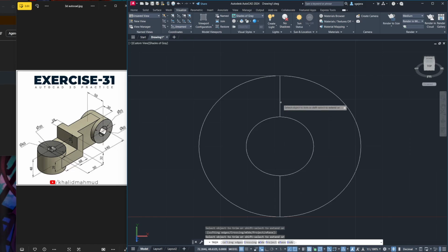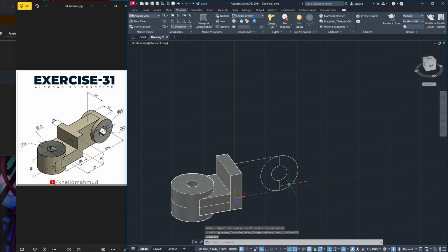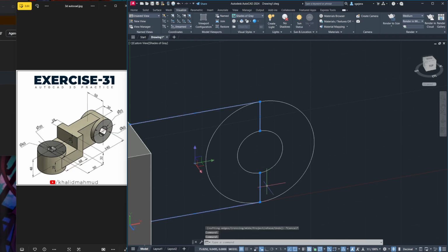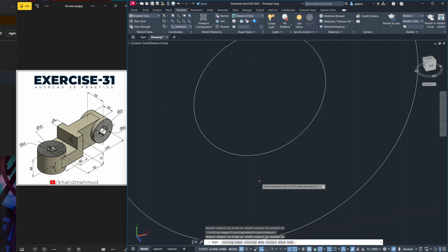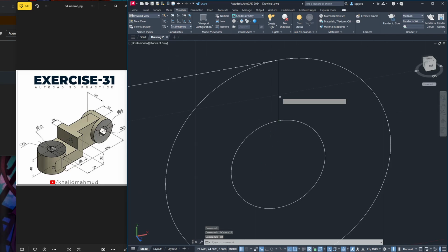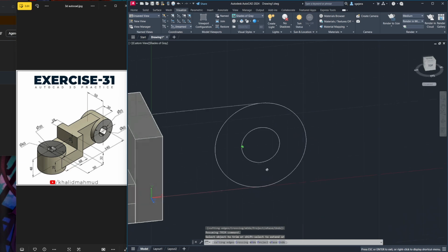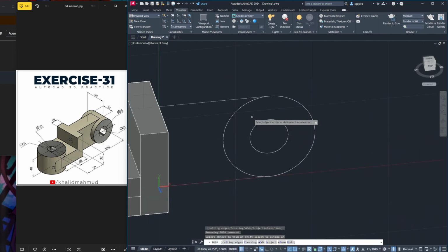And we can also trim this. But why is everything disappearing? Anyway, I'll trim that later. If I trim this, will the line be retained? Correct. And let me trim this as well. Trim. So that's the profile we want, because if we press pull now, it's easier.